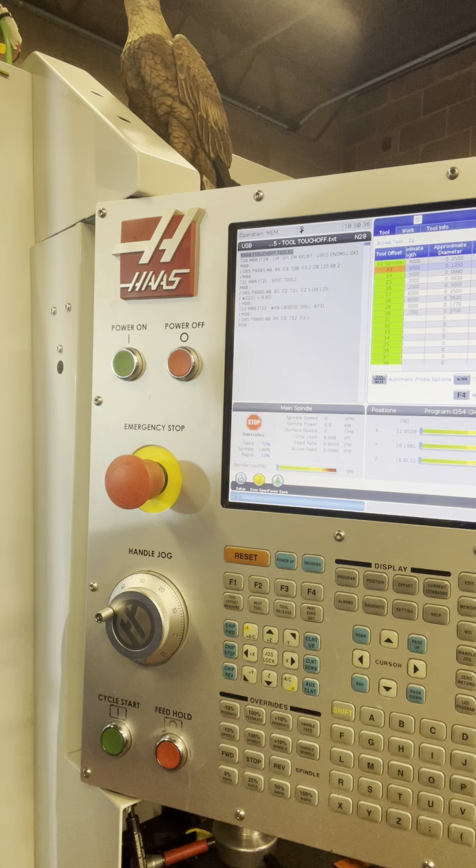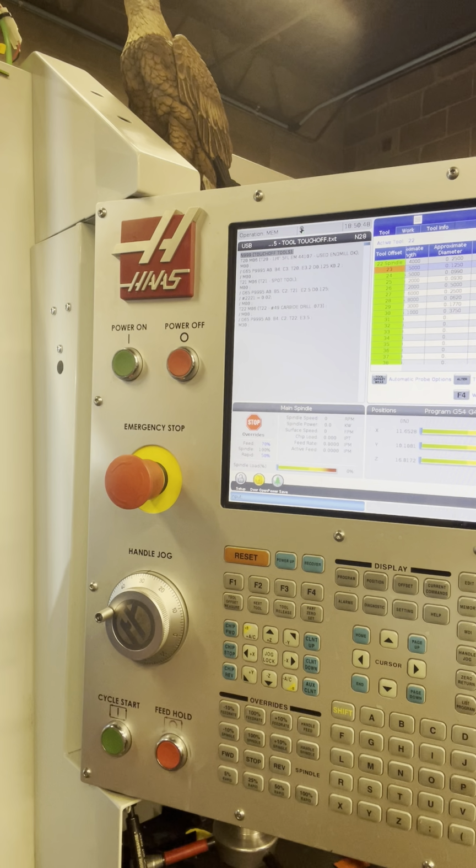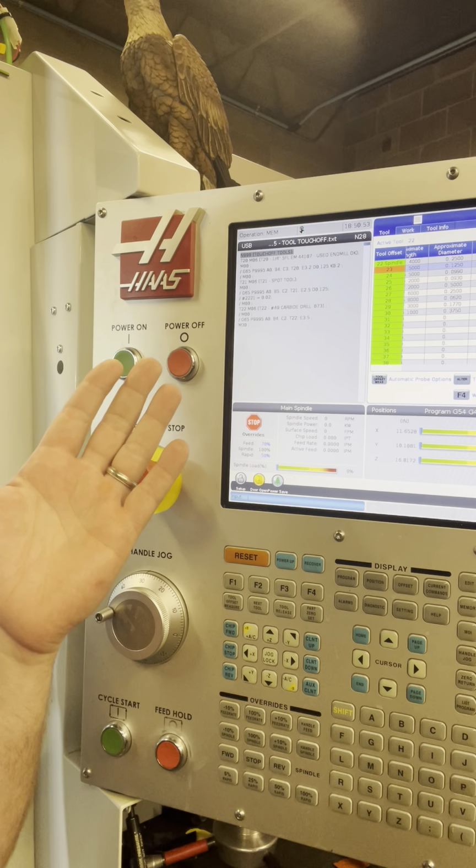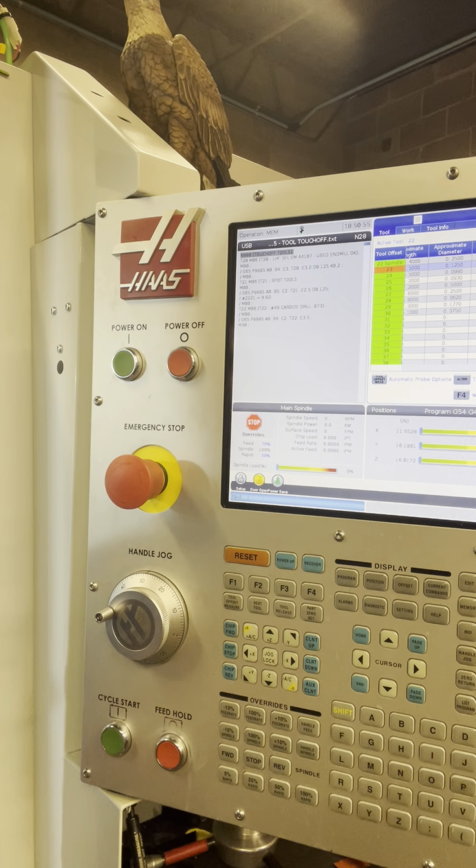The really good part about this is it kind of gets you through a process of how we're going to set up this job. I have these in order. It's 20, 21, 22. It doesn't have to be in order. The machine's gonna give me the pocket for T21 into the spindle, so I know I'm putting T21 in there when that is up in the program here.